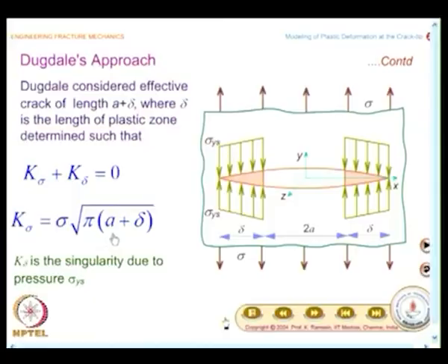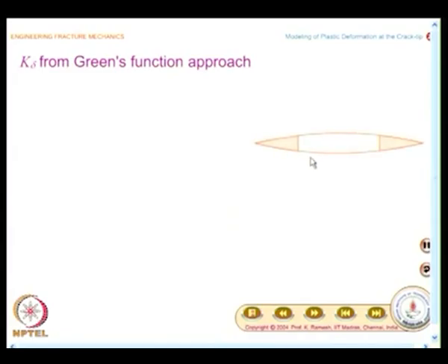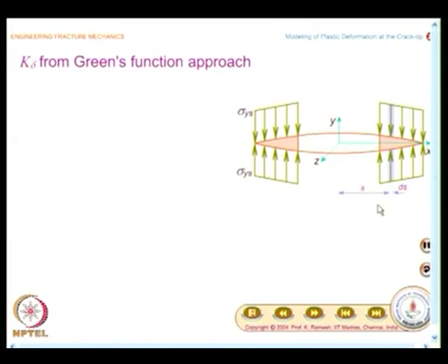And can you find some similarity here to find out how to evaluate the stress intensity factor in the presence of sigma ys? The crack faces are symmetrically loaded, that you can recognize, and in fact we have done evaluation of stress intensity factor for a symmetric concentrated load acting on the crack surface earlier. In fact, you could invoke that and write an expression. The difference is, you are having a distributed loading, there we had looked at a concentrated load.